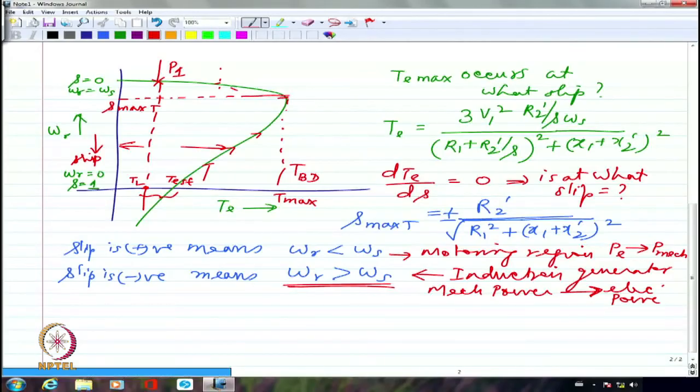On the other hand, instead of 8 people, say 18 people have gotten into the elevator. The torque demand is very large. If the torque demand happens to be somewhere here, the machine will not start at all.